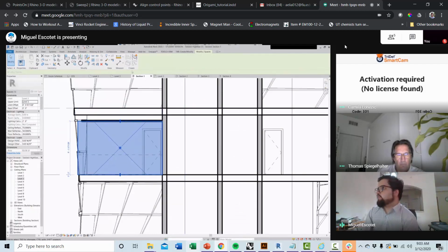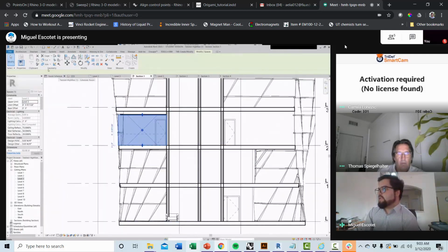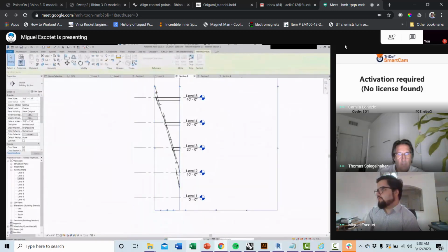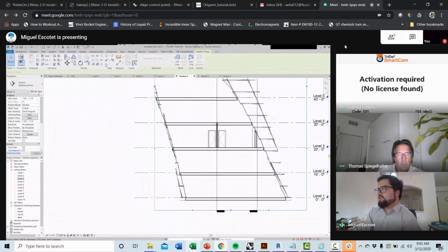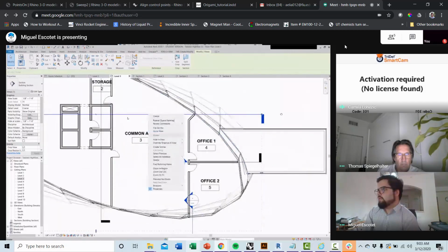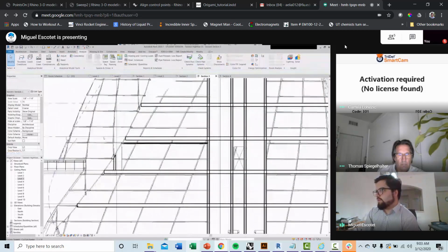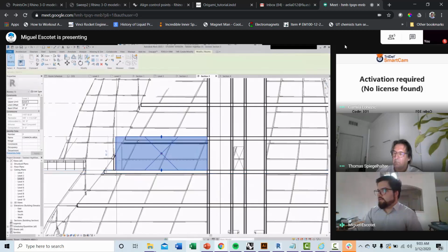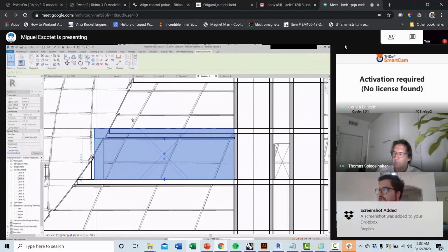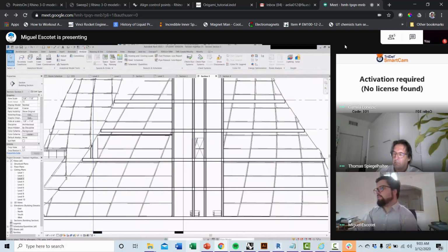Okay. The next one is we should be checking other ceilings, and other sections. If we come to level 3 again, we have this section here. And here we can see that this is our ceiling, and it's happening the same. So what we need to do is reduce it. This will reduce the cubic feet that are going to be analyzed later on. From here we should go.